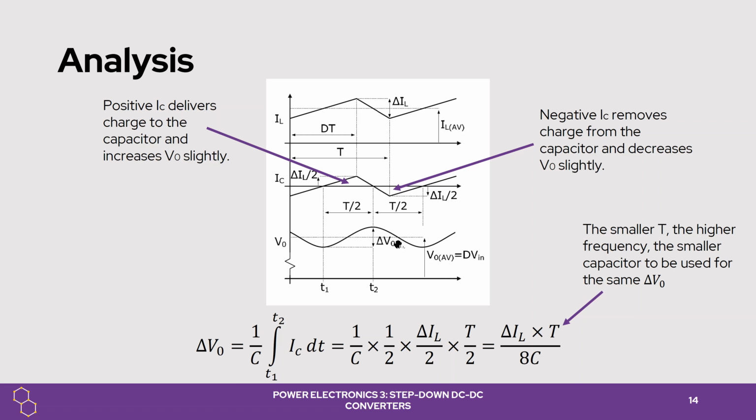And how we can reduce this ripple is done by using higher frequency switching with the transistor. Instead of using big capacitors, which is really not feasible, we just use higher frequency switching using better switches, which means a better transistor and a higher frequency transistor. And that is all done using a very controllable transistor, using the driver circuit.